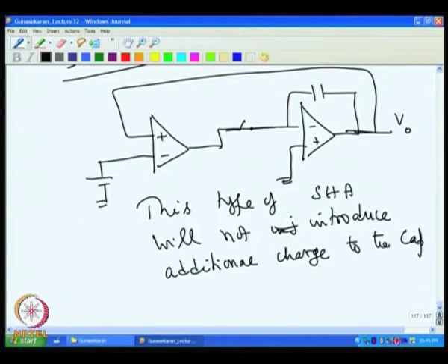And this also works extremely well, but in today's world the sample and hold amplifiers are rarely used because of the additional overhead, plus the time that it takes to charge and the other oscillation problems. People are getting away with the sample amplifier and trying to find several other shortcuts to have an accurate conversion.